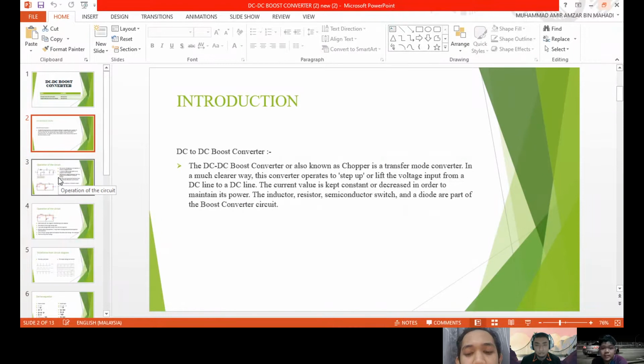Attach the voltage measurement block to the load in order to calculate the output voltage. Capture and store the output voltage waveform seen in the scope by using the selected frequency and duty ratio. Identify the ripple of output voltage from the simulation.